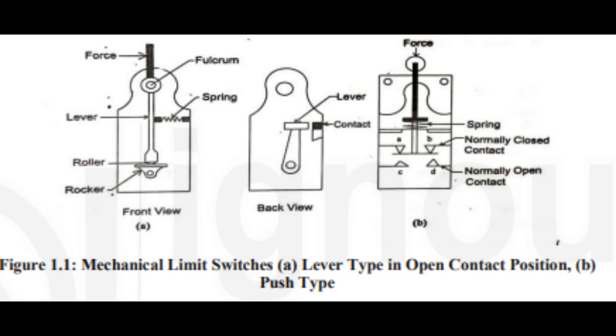Limit switches come in several varieties and designs. Figure 1.1 simply shows two concepts. They are designed for heavy-duty applications in which there is physical contact between the actuator and the process being sensed. For example, limit switches are often used on machine tools to limit the travel of a machine axis.